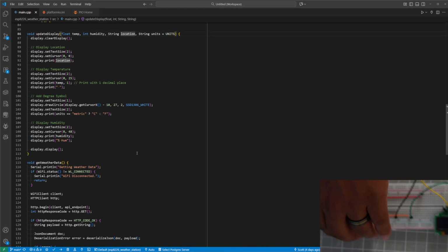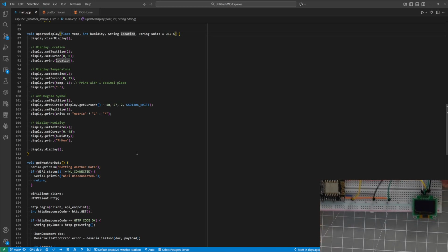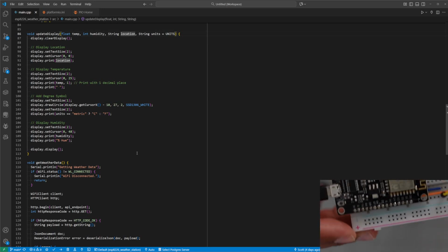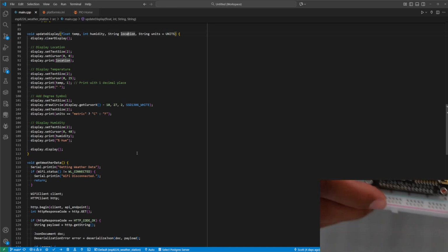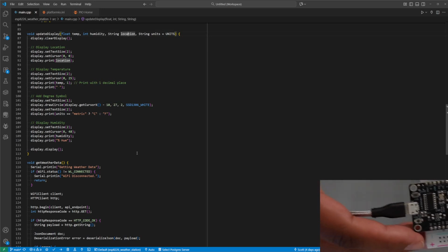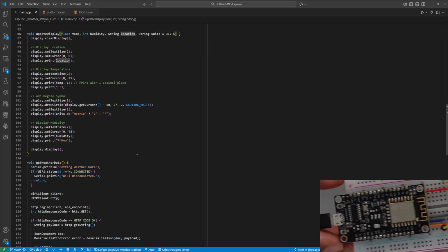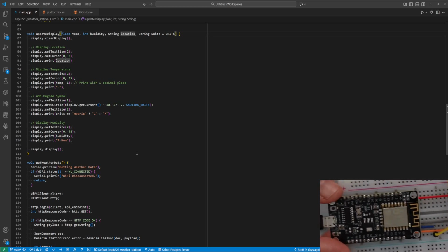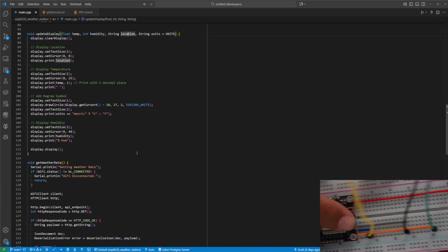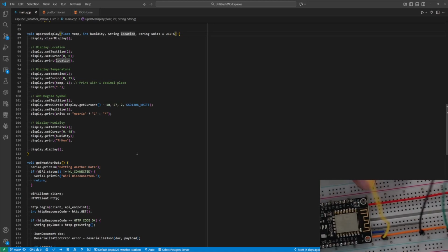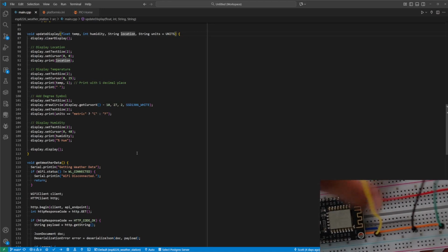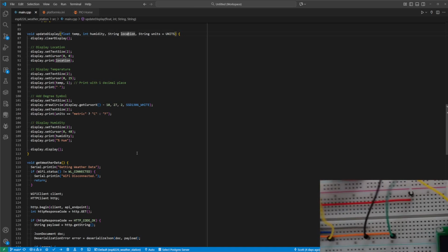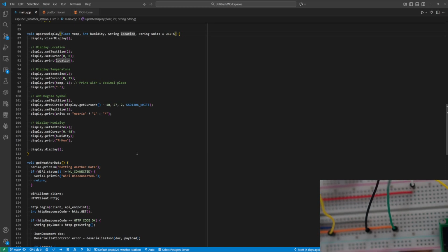If we go and look and see how we have this wired up, I'll try my best to get this in here. We have the ESP8266 here, where because the width of the board is also the same width as the inner rows of the breadboard, what I've had to do is actually run some extender cables from underneath it, because it runs parallel on the breadboard here, to reach out so that I can actually run these jumper wires to the proper connections.